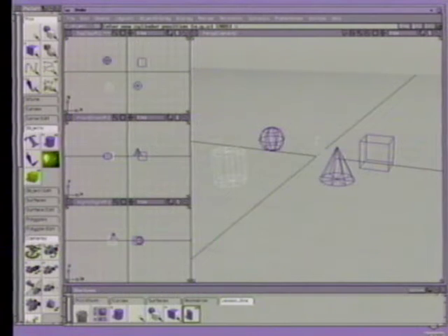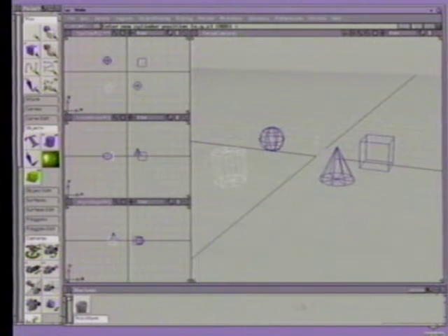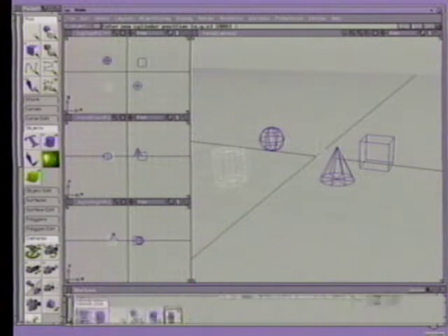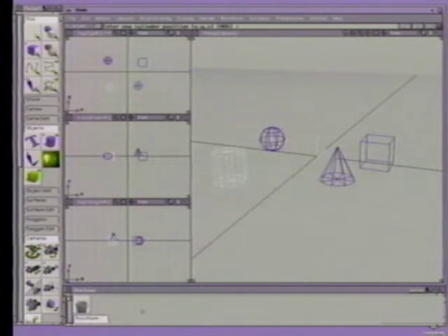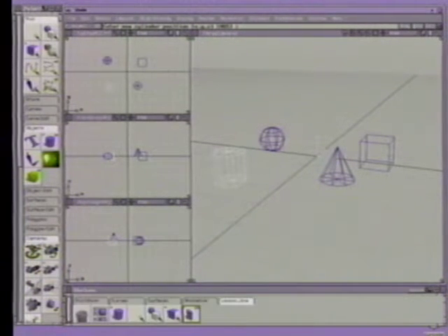On the tool shelf, select the Orient button next to the Option menu. This reorients the shelf tabs in a vertical organization similar to the tool palette. Use the scroll bar on the left to scroll between the various shelves. Click again on the Orient button to return the shelf to its horizontal orientation.